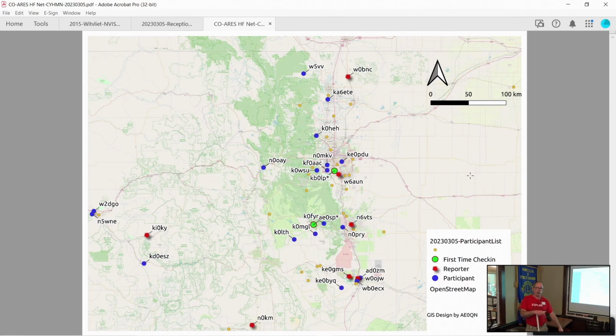Well, the antenna 14 inches off the ground. You'll see some websites where people talk about NVIS antennas 10 inches off the ground being really great. I wouldn't bet my life on it. If you had to set one up down low for some reason, you could, and you could give it a try. Again, my experience, 15 feet. It's not that hard to get a wire 15 feet in the air out in the woods.